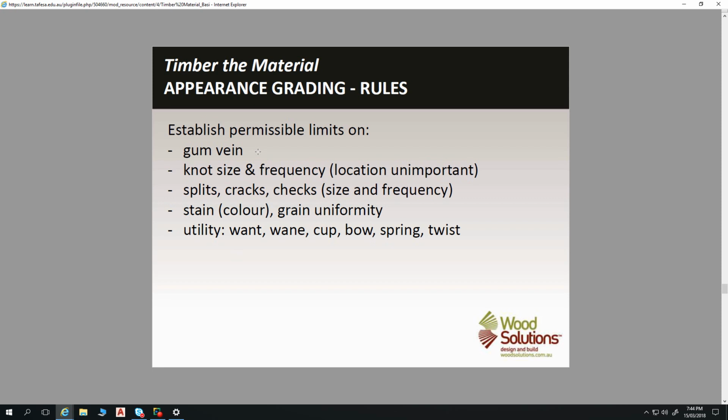You've got your piece of timber, then you've got your various different grains, and then you've got a thing happening there like that, and a bit of a thing there like that. That's your live knot. Your dead knot will have a much darker ring around it. It might be quite dark itself, and it's loose in there.